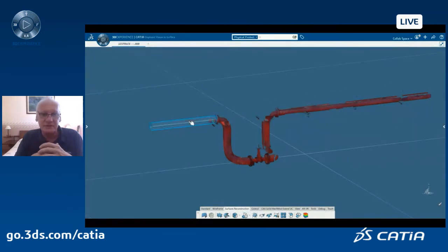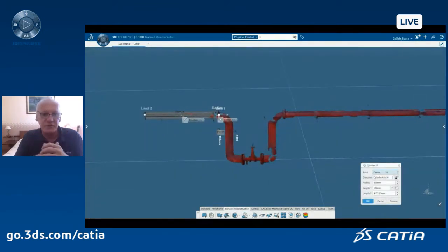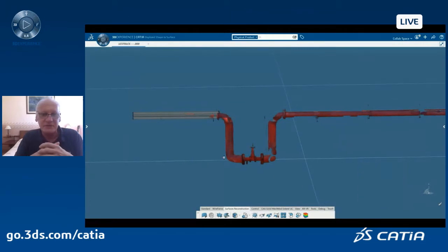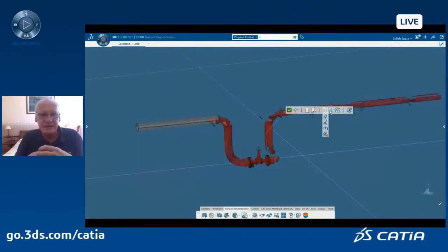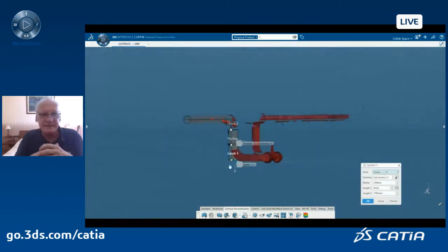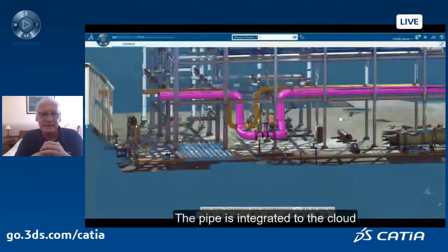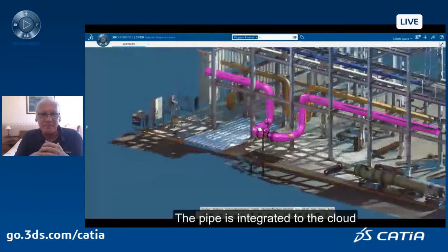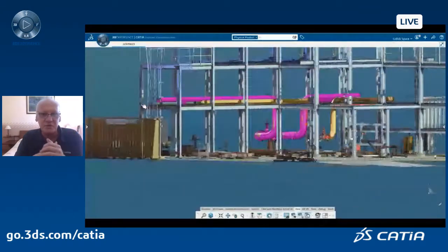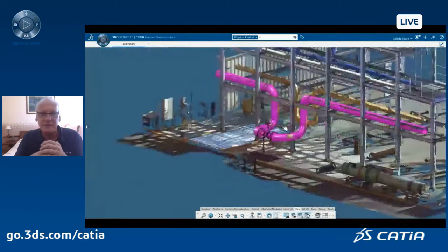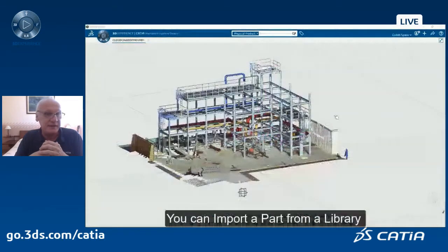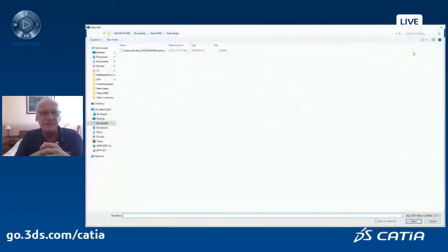We can also, if we want, redesign manually, for example, these components. Here, CATIA will automatically recognize cylinders, planes, planar surfaces, tori, cones, and so you can redesign, but you can also modify very easily those cylinders, those dimensions. And here, I can integrate again my pipe plus my equipment coming from the database, and let's say pipe design on the fly with a CATIA canonical surfaces recognition capability.